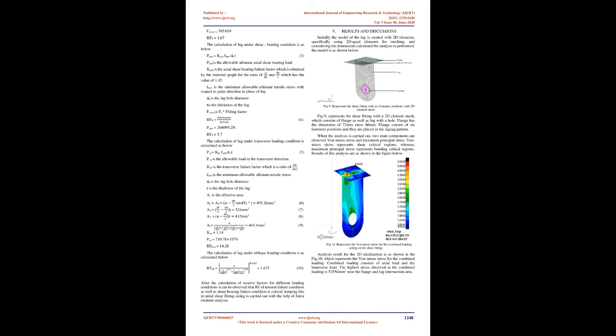Fitting factor equals 1.15. Since the loading for the front fitting is 12,833 in Fx direction and 137,840 in the Fz direction, initial lug dimensions are assumed as width, W, equals 60 mm. Hole diameter, DH, equals 24 mm. Distance from center of circle to end of the lug is, A, equals 36 mm. Thickness of the lug equals 18 mm. Fig 7 represents the specification of the lug.